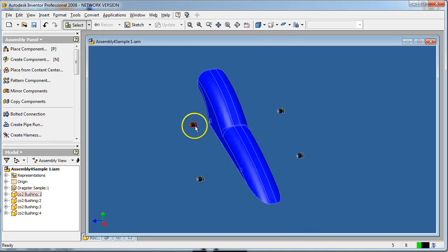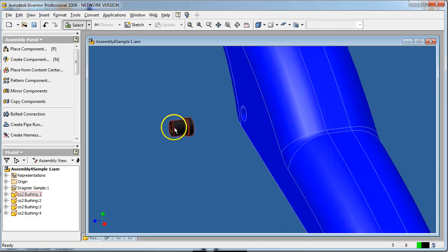So I'm going to zoom in on the first bushing, and I notice that it's not rotated the correct way. That's okay. This smaller part will be inserted into the axle hole so that later the axle will sit nicely inside the bushing so that there's minimal friction on the axle with the block itself. So the axle will only be rubbing against the bushing on this side and on the opposite side, so that we are reducing resistance here.